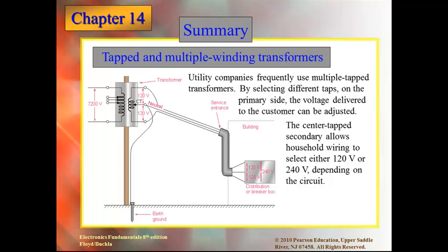Here's an illustration of what we've been talking about. Say for the transformer outside your house, utility puts it up on the line, and they've got 7,160 volts coming in instead of the 7,200 that they're indicating on the slide. They can move on to one of those other taps to make sure that the secondary side you get 120, 240 or as close as possible, inside your house. And so they might have to go down, one or even two of those taps to adjust that.